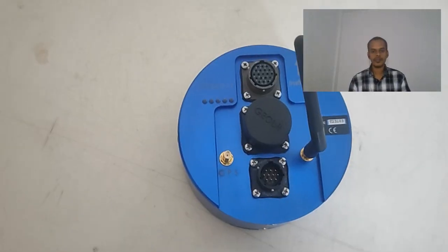So now we are looking at a digitizer or a recorder. This is the most crucial part in a seismic station, because this is having all the programs, and this is having the storage. This will gather the information, and it will convert the analog into digital, and this will be sending the data to the server, and this is giving the power to the seismic sensor.